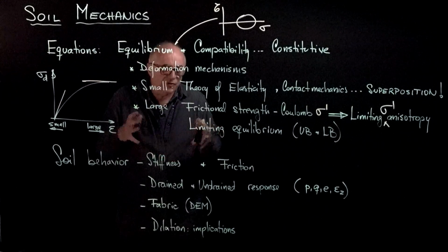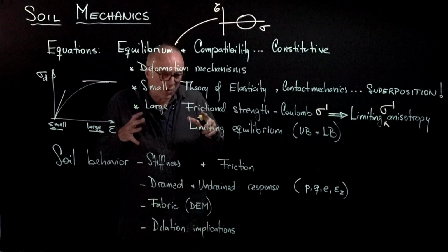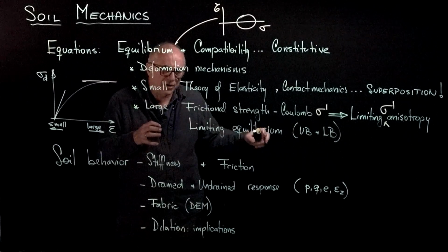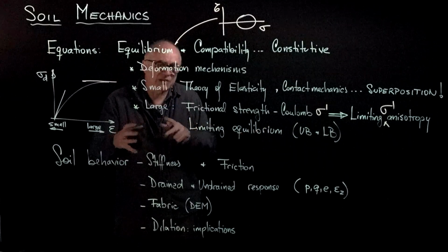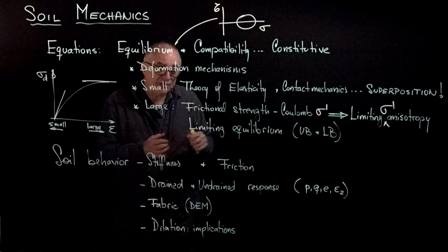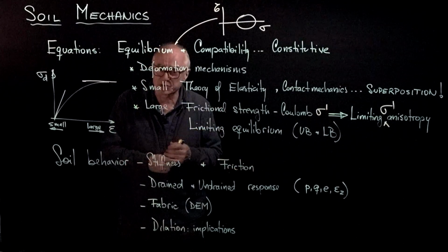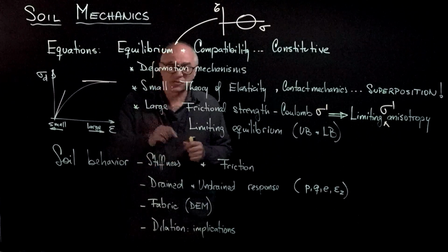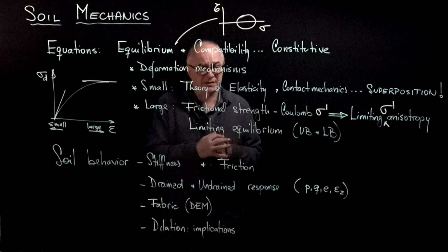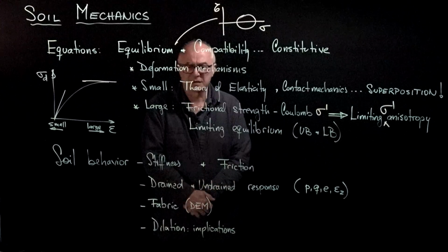Now, all this evolution in the behavior of soils can happen while the liquid inside the soil can escape or be pulled in to accommodate for expansions and contractions. However, if that doesn't happen because the rate of loading is much faster than the rate of pore pressure dissipation, we're going to create changes in pore fluid pressure, which means that we're going to change the effective stress. And so we need to understand the drained and undrained response of soils very well.